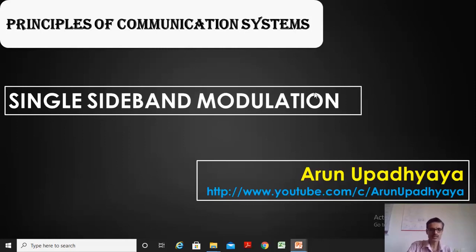But we are not going to save anything in terms of the bandwidth. The bandwidth requirement in the case of double sideband full carrier and double sideband suppressed carrier is 2W Hz, assuming that W is the message bandwidth, or the highest frequency in the message spectrum, a low pass signal.